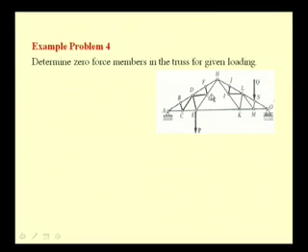Same way, if we analyze this joint at G, we have this force in this member FG is 0 and this member EG and GH are collinear, and if a force exists in DG, it cannot be balanced because we have already determined the force in FG to be 0. So, thus we see that this member DG as well as DC are also zero force members.